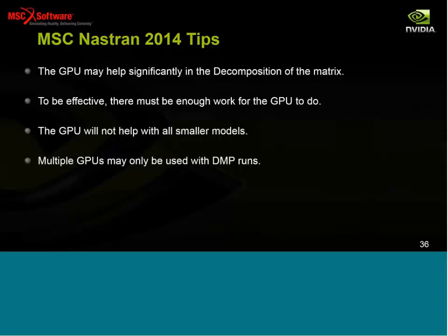Solid elements are really the best, but you can see that we do get performance out of shell elements as well. Generally, it's not helpful for smaller models to use the GPU just because there's not enough work, and multiple GPUs can be beneficial.